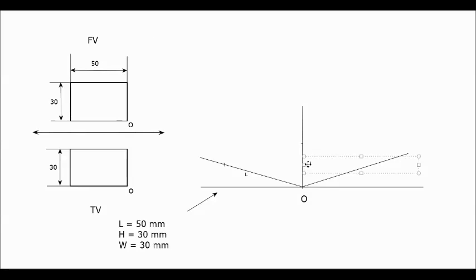Now for marking the width, you have to consider this side view. As the front view is known, obviously on the right side of the origin on the vertical plane, your side view lies. The base of the side view is the width of your object. So mark 30 mm from the origin point on the right side inclined line, and we have marked the width of the object.